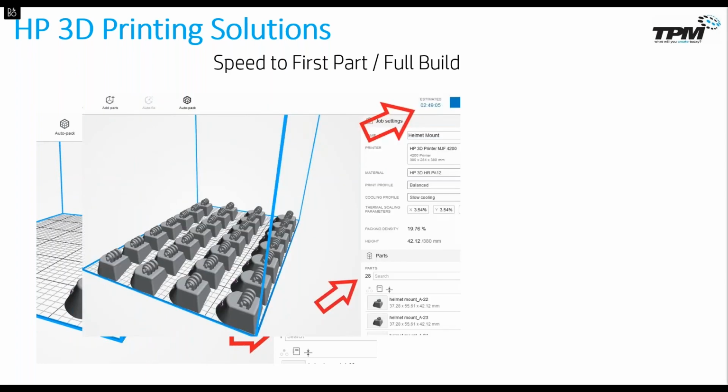If I fill up the entire XY plane on the lower level of that build platform, I now have 28 parts, and you can see that the estimated build time is still 2 hours, 49 minutes, and 5 seconds. That is because with multi-jet fusion, it is sort of like a 2D process. For each layer that it performs, it prints the same amount of material. So if you have 16 parts that all occupy the same space on the bottom, it's going to print in the exact same time as if you had one.